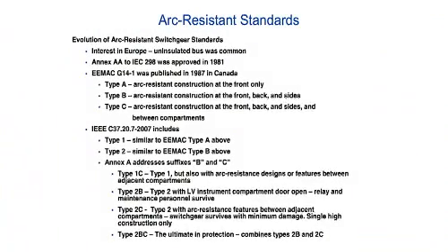Very few people actually need to get into the breaker compartment as opposed to resetting relays or low voltage control or whatever it may happen to be. Okay? So that's why 2B is becoming virtually the standard in the United States. In other words, when people talk of arc-resistant switchgear, most of the time they're talking about type 2B switchgear.